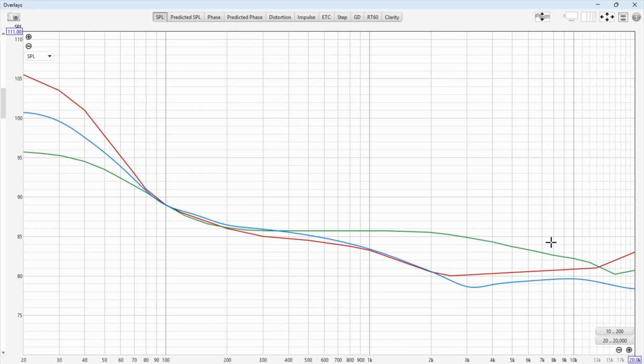And so what you can see here is Audio Frog's, this green curve here. It's got a lot of mid-range from about 400 Hertz all the way to about 9 to 10,000, even up to 13,000 Hertz. There's this big band over. Now, that's nice, but in a car, it could be a little bright or it could even be kind of irritating on the ears. But, you know, your mileage may vary. And then we can see Resonix curve, that's Nick's curve. You can see the mid bass climbs, levels out, and he has a nice drop here from about 400 Hertz all the way to about 3000.